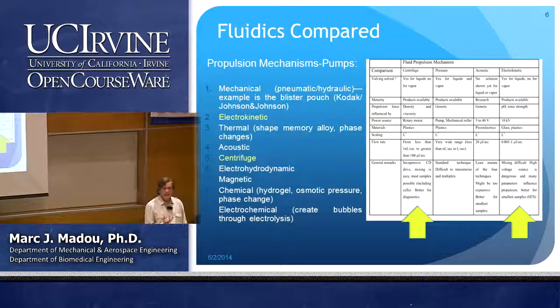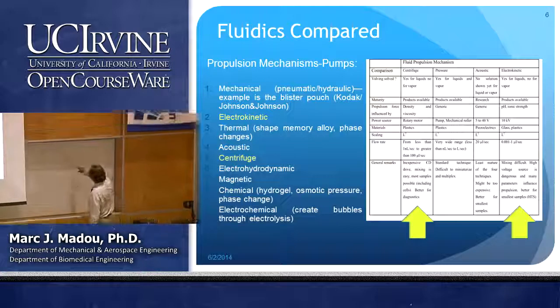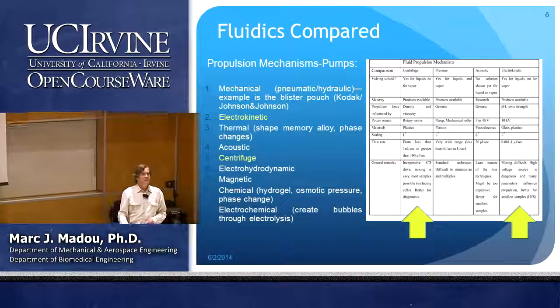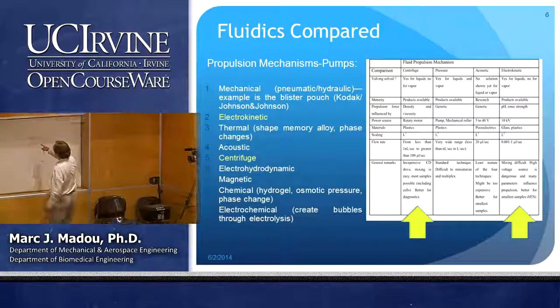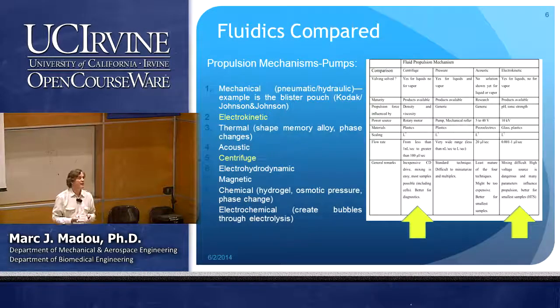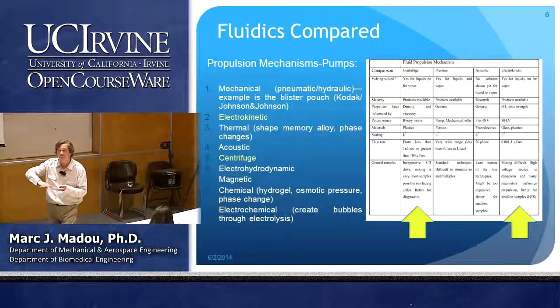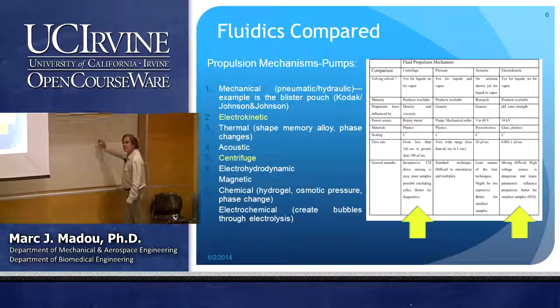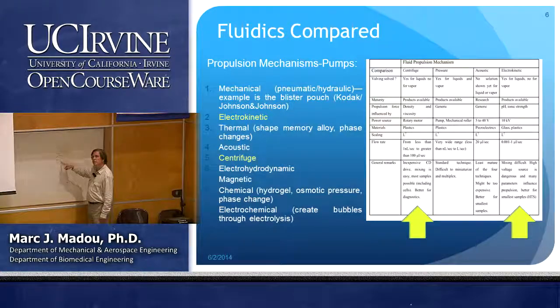But say I'm not ready to bring this liquid from here to here. In other words, I have that CD sitting there with some liquids, maybe for 6 months, right? What will happen with this liquid? Will this be a barrier? It will not, because vapor will distribute all over. And so after less than 6 months, maybe even after a couple of days, that liquid, because of the vapor pressure, will be everywhere. Interesting, right? Because that means that this capillary here can be a barrier for liquid, but not for vapor. Do you follow that? Right?